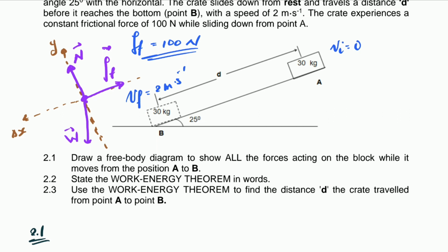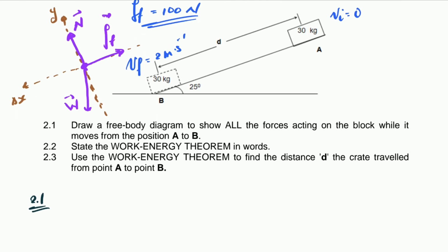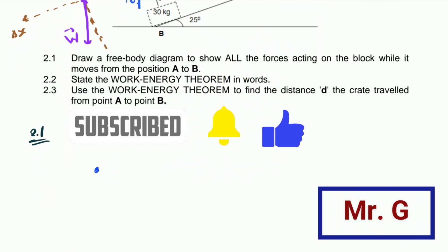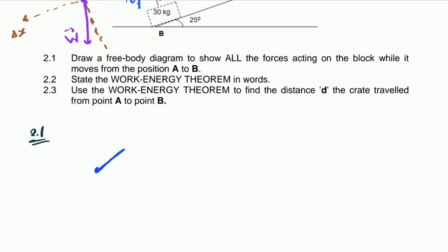So now, saying that, all you have to do is transfer this one without the axis to this question. And that is not that bad. It will be quite simple. This is the object. Frictional force is going to be pointing in this direction. It's in opposite direction of motion. Perpendicular to frictional force, make sure this force is perpendicular. This is the normal force. What I mean is make sure this angle here is 90 degrees. This 90 is not part of the free body diagram, and then the weight pointing down, and this is the free body diagram they're asking you to do in question 2.1.